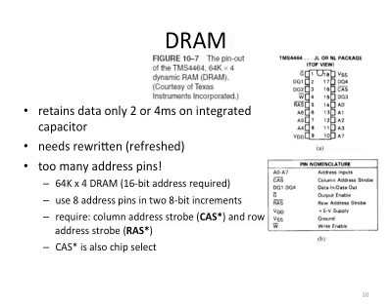To address this issue, DRAM designs often use split address pins. The way it works is that, for example, for these 64K locations, we need conceptually 16 pins, but physically we only use 8 address pins. How is that possible? If you have only 8 address pins connected to this chip and you want to access 64K locations, one address pin can do 2 different things. So we essentially do time multiplexing.